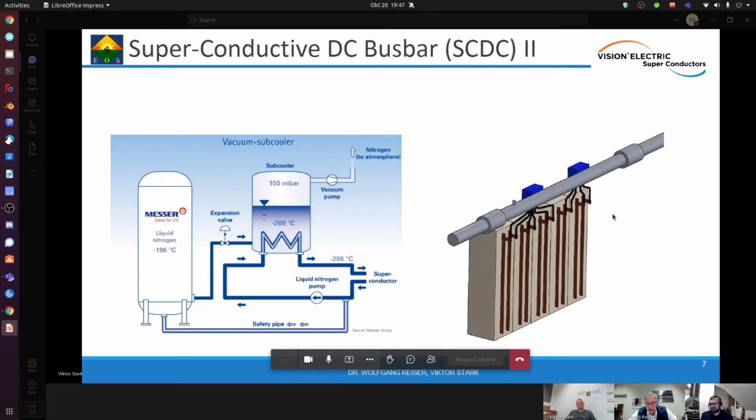It is not very high in costs. The break-even point between supplying cooling power with liquid nitrogen and the other possibility, using cooling machines, is at about 10 cents per kilowatt hour in energy costs.